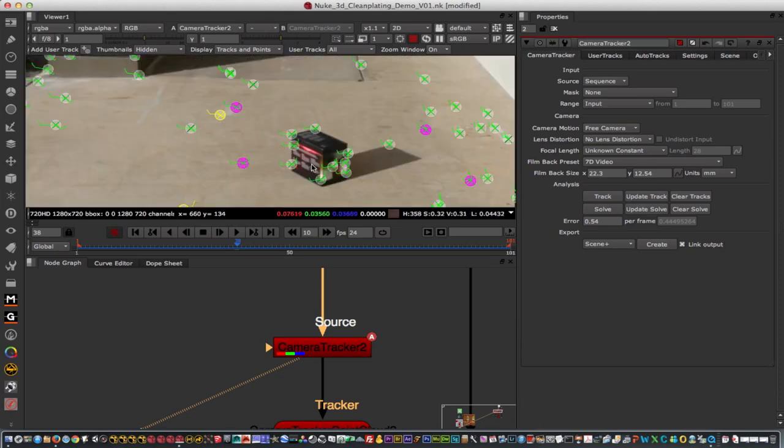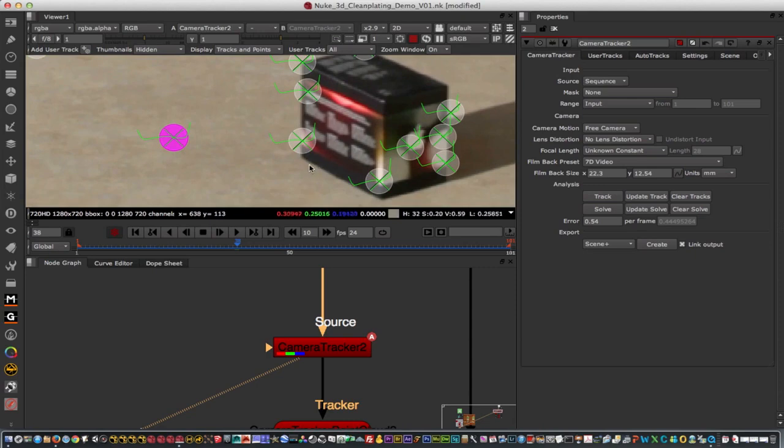Scale is relative essentially in the 3D world, but what I'm going to say is from this point to this point, I want those 2 points to be exactly 1 grid unit apart. In this case, 1 grid unit means 1 centimeter apart, even though in the real world that will probably be 1 foot. Again, the scale is relative. I'm going to select 2 points that I want to set the distance constraint to, right click, go to the scene and add scale distance.